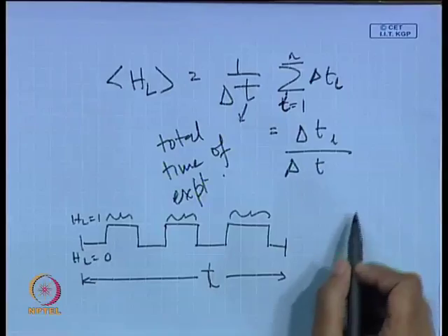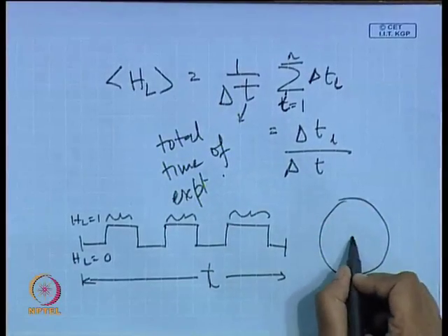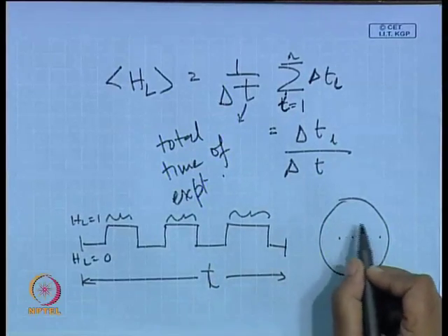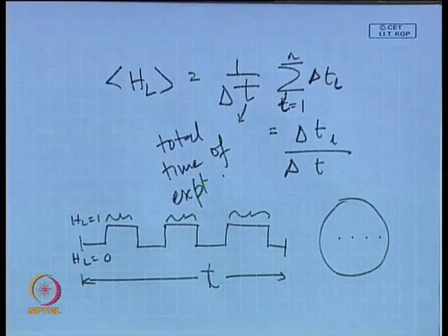If you know the time average void fraction at each and every point, from there you can find out the voidage profile or the distribution of the voids, and accordingly you can play with it, control it and manipulate it, or you can at least have an idea of what it is, so that if you cannot do anything with it, you can at least incorporate it in your models.